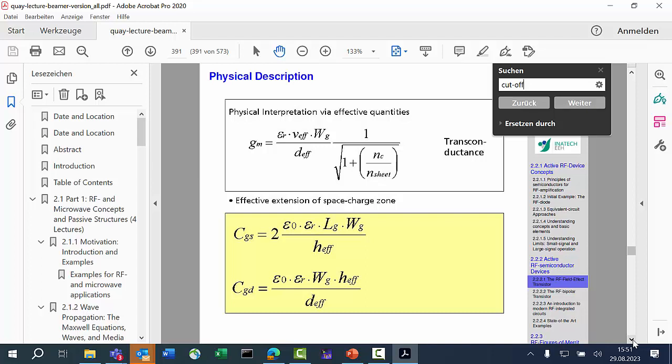In CMOS, we call that the oxide thickness. So you make it thinner, not only in the size, but also you make the whole thing thinner. You need that to control the current. At the same time, from the simple capacitor equation, you can see that by reducing the distance of the carriers to the contact, you also increase the capacitance, which means that you are not winning anything in the ratio of gm over Cgs. So there's no winning of speeding up.